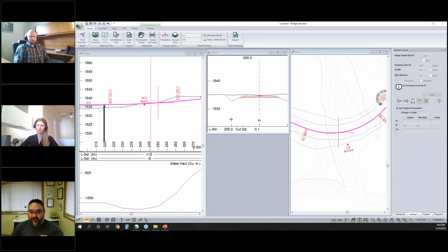So I would say, rule of thumb, if something is 1 meter deep and you think you can cut it without having a huge problem with water or getting rid of that material, it's usually a bit of a no-brainer to just get that out of there and put your material right down on something underneath.